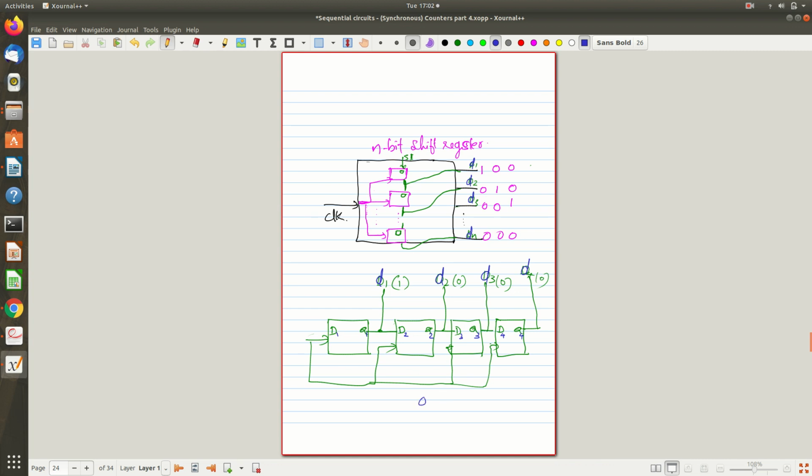If you are analyzing the outputs Q1, Q2, Q3 and Q4, you will see that initially it is 1 0 0 0, and then we apply clock pulses. Once I trap this 1 and 0 0 0, initialized like that, I'm not giving any other input. You can trap this input in a serial manner or a parallel manner, whichever you choose. But after this, just remove the input completely, so that after every clock cycle the shifting happens.